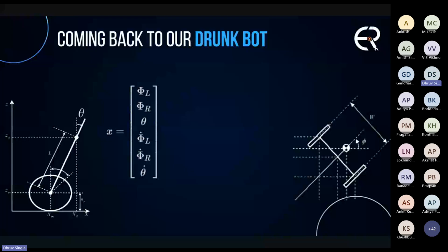However, while building this model, the self-balancing boat in MATLAB and Simulink, we will only consider one-dimensional motion in translation. For that motion, phi L and phi R become equal, so our only state variables will be x and theta. However, here we consider two-dimensional motion. As we can see, the boat is tilted by some angle phi from the horizontal, due to the difference in rotation of the left and right wings. So for this system, we define phi L, phi R and theta as separate variables.